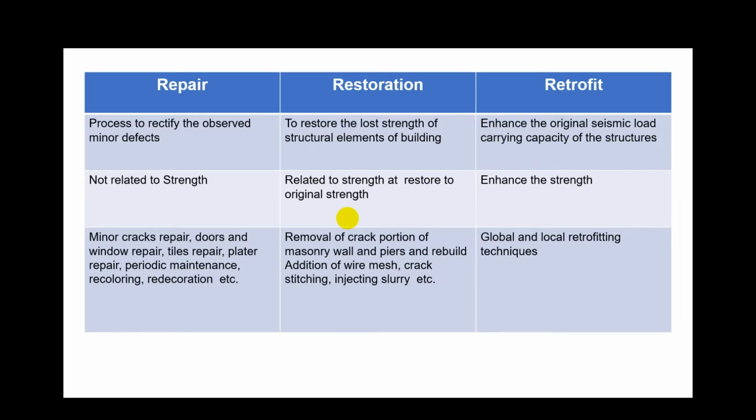It means with the restoration technique, the original strength of the structure is regained, but not enhanced. In repair, the strength is not achieved. The repair is to maintain the building for aesthetic purposes, whereas restoration is to regain the original strength. But if we look into the retrofit, it is the process to enhance the original seismic load capacity of the structure, which can increase the ultimate load carrying capacity of the structure as well as the ductility or deformation capacity of the structural elements.